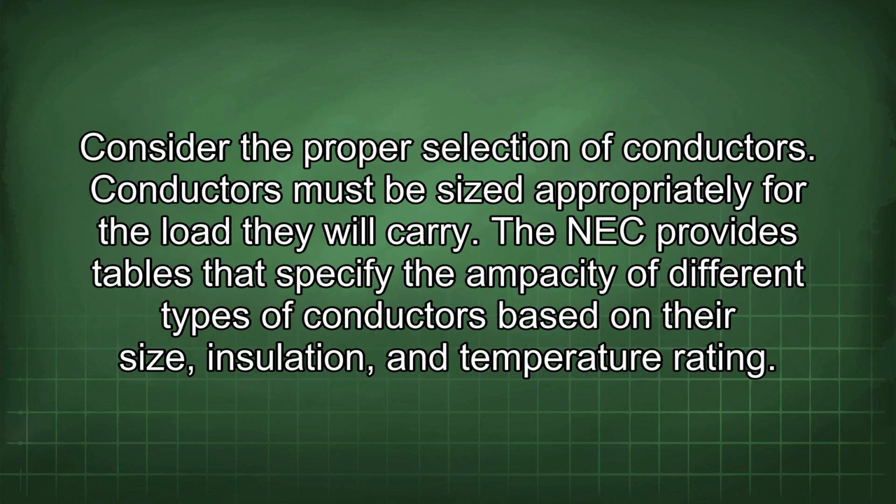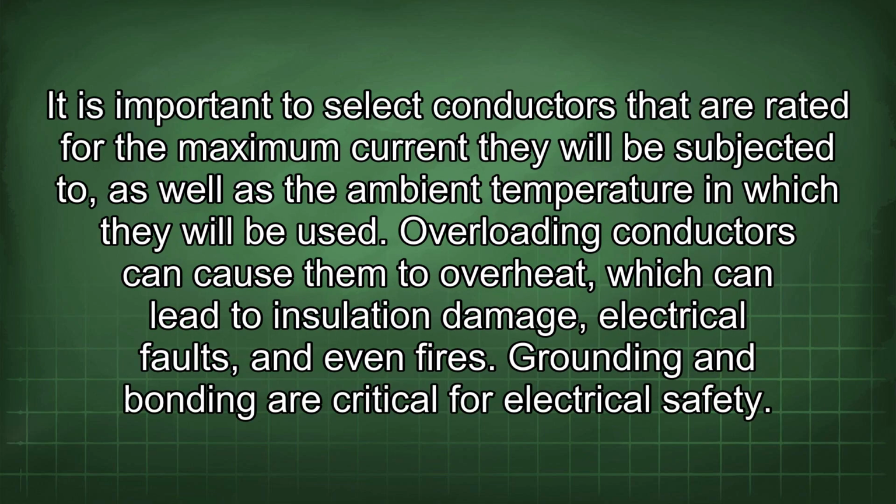Consider the proper selection of conductors. Conductors must be sized appropriately for the load they will carry. The NEC provides tables that specify the ampacity of different types of conductors based on their size, insulation, and temperature rating. It is important to select conductors that are rated for the maximum current they will be subjected to, as well as the ambient temperature in which they will be used. Overloading conductors can cause them to overheat, which can lead to insulation damage, electrical faults, and even fires.